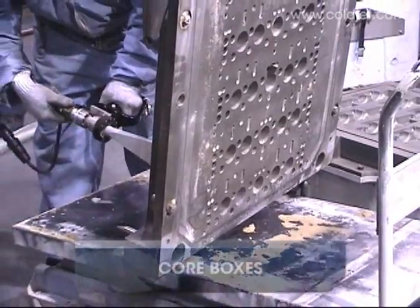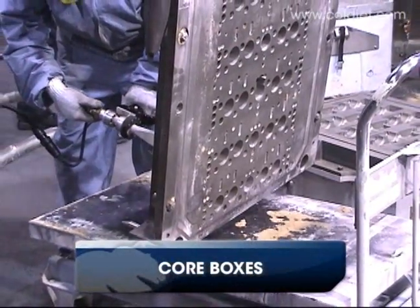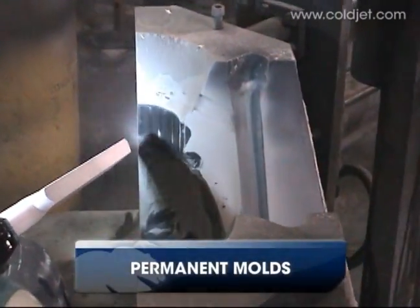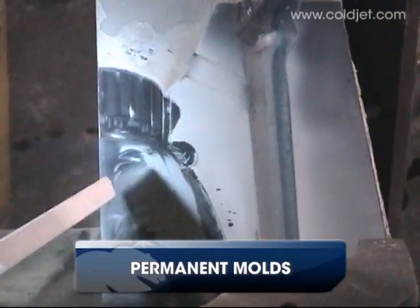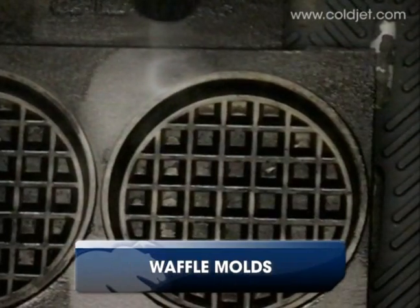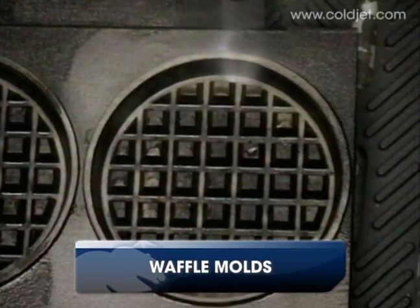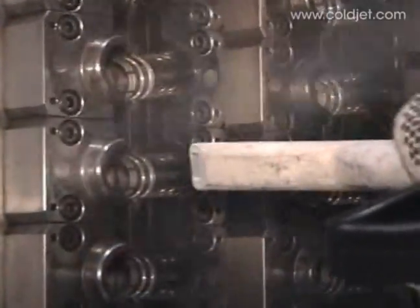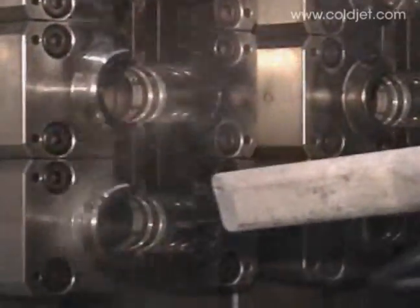As an example, in the foundry industry, dry ice blasting is ideally suited to clean hot core boxes and permanent molds in place. Mold cleaning is a common dry ice blasting application, not only in foundries, but also in food manufacturing and in rubber and plastics molding. Downtime that was once measured in hours, or sometimes even days, is now measured in minutes.